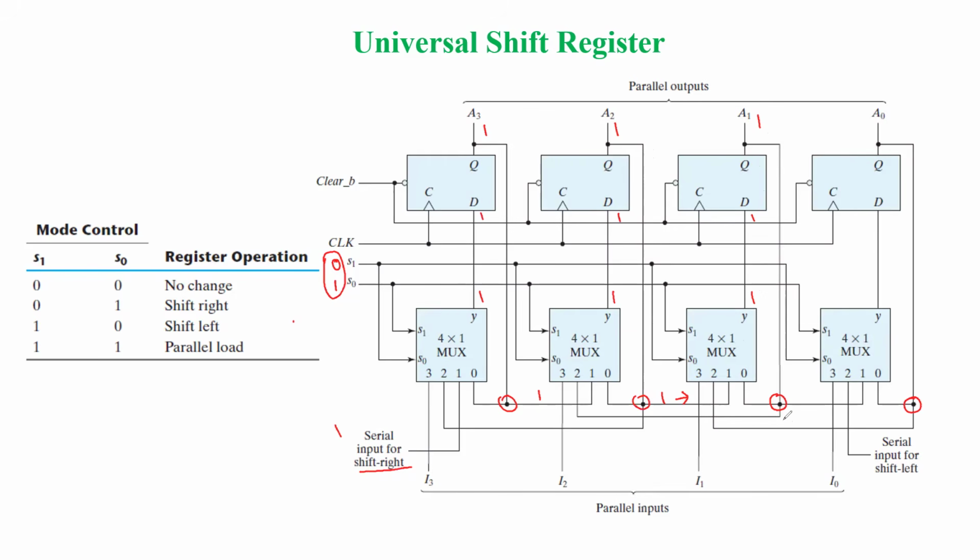Again this A1 is connected to port 1 of the next multiplexer, available at Y, the output of the multiplexer. Again it is input to the D flip-flop, which is available at A0. So like this, the first bit is available at the output A0. We have already seen how shifting takes place in the case of serial in and serial out.